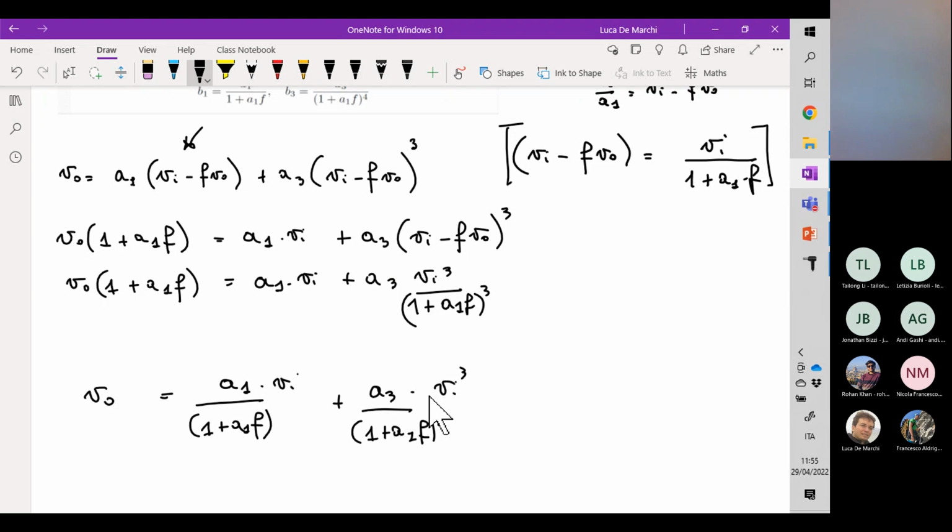Okay, so taking into account that omega 0 dB is defined as the frequency which generates this equation, so the loop gain equal to unity, this implies that in this specific position of the frequency axis, the gain associated to the direct path is equal to 1 over f, because A of j omega null times f equal to 1 implies this equation.